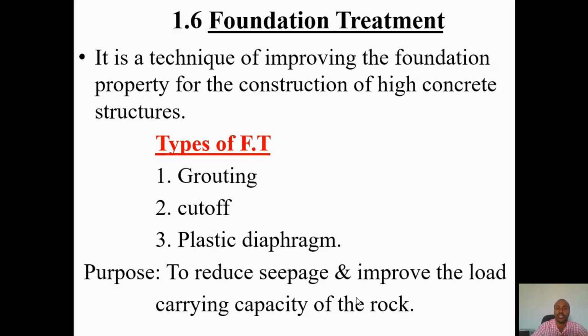Okay, so this is, I think, the last topic for chapter 1, foundation treatment. So why do you treat the foundation? The foundation must be treated. If you have weak zones or cavity holes, sink holes, or fracture zones, you need what? To treat these weak zones. So you may have void spaces inside, under the subsurface, below the foundation, or on the abutment. So you need to fill the void spaces so that it will be tight against flow of water.